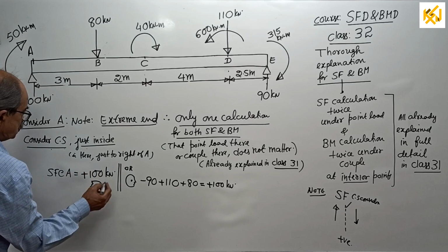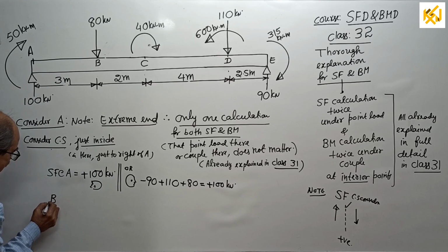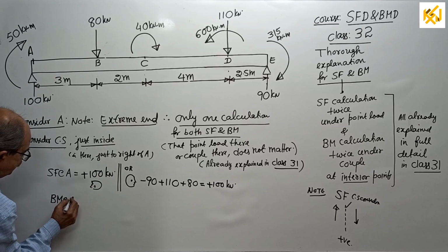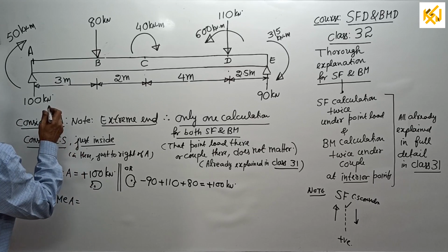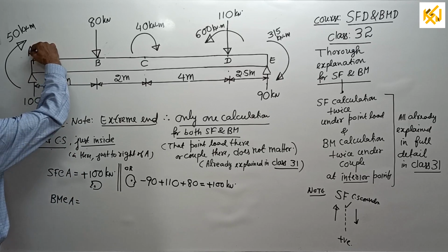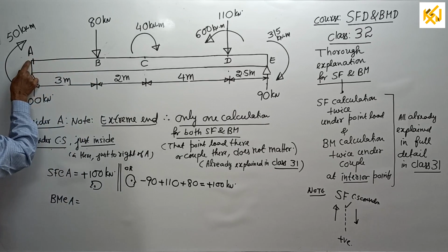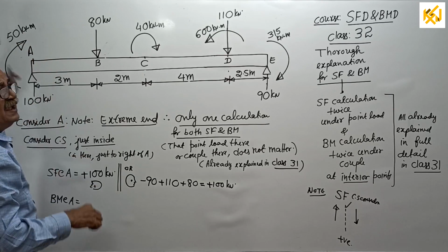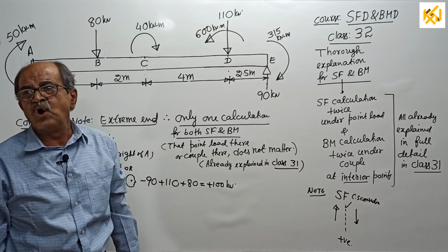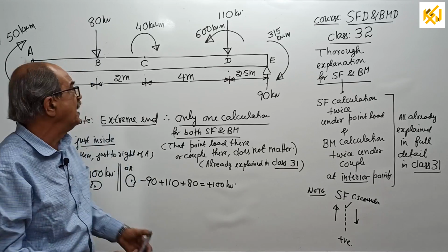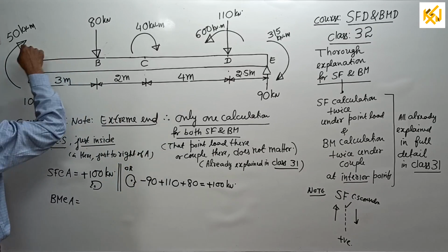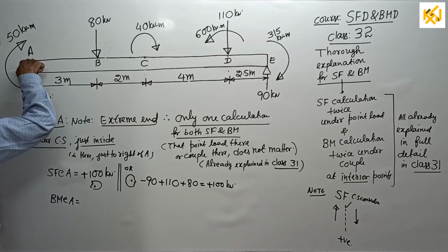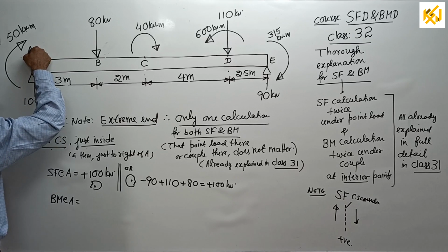Next, shear force over. Next I want bending moment at A. See, you are slightly inside here. This distance is so small that if you take 100 into it, it is 0.00001, so 0 only. Therefore, remember, even though you are here, actually you are here only, slightly inside.